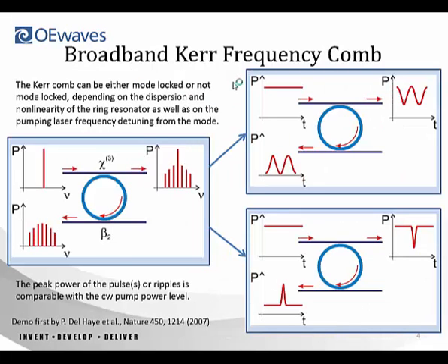This is what was observed recently, starting I think in 2014 with the demonstration by Tobias Kippenberg at EPFL, that if we pump a resonator strongly enough, we can get broad frequency combs that correspond to a train of optical pulses. Importantly, depending on the configuration of our cavity, we can observe either dark pulses or bright pulses in the system. So within the resonator, we can generate a pulse. At some optimum condition, all harmonics become mode locked, and inside the cavity a pulse is excited. What is interesting here is that if we use a drop configuration, we will see a bright pulse. But if we have an add configuration for the coupler, we observe a dark pulse there. Usually people don't look at dark pulses, they just remove the carrier and look for bright pulses. However, dark pulses are still there.